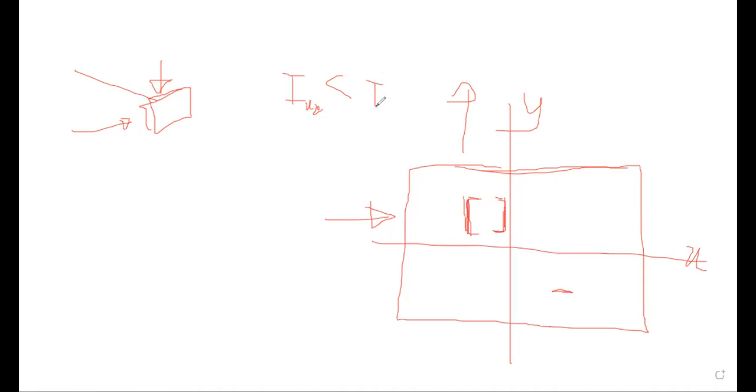It's not actually Iyy, so you will know the reason later. Even though the Ixx is low, these walls are now making the model fairly stiffer in x direction than the y direction. That's why the first mode is in this way now, right?